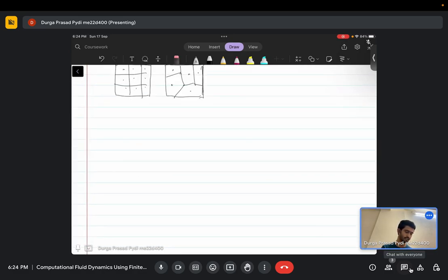So you are essentially asking, when we are using unstructured meshes, you are getting a secondary gradient term, but that is essentially going to your B term, right? No, I'm talking about the non-orthogonal meshes. Yeah, even in the non-orthogonal mesh, your secondary gradient term will essentially go into your B part. So at that time, if we analyze the boundedness criteria, they will find that it will not be bounded.